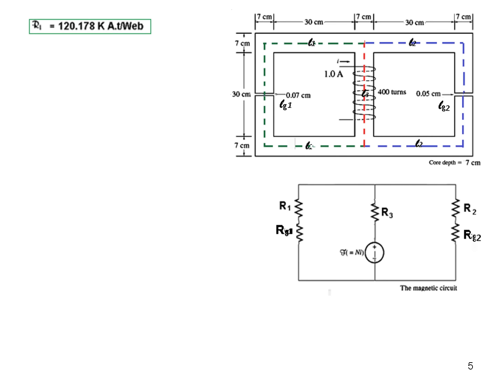Now the reluctance of the right hand side core: since the dimensions are all the same, the reluctance of the right hand core material is also the same. So instead of calculating, we can just copy R1 here, it will be the same value.